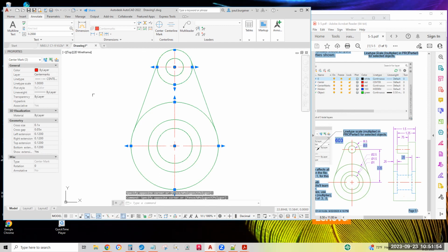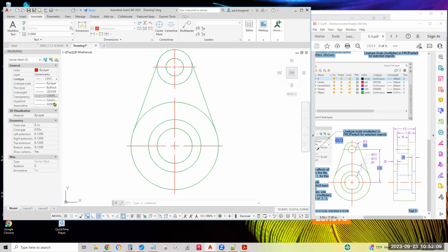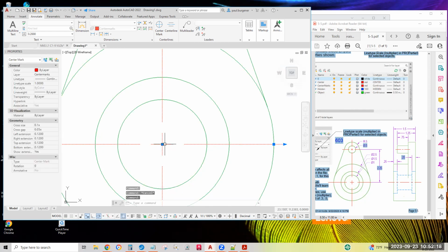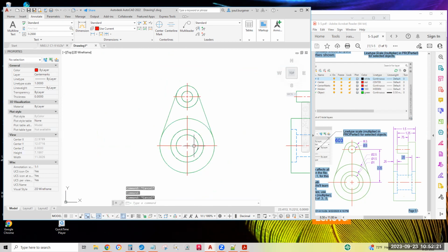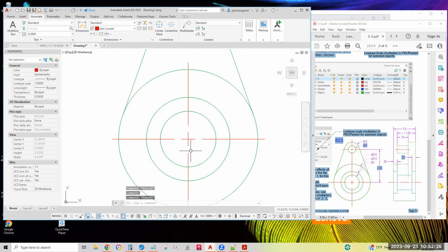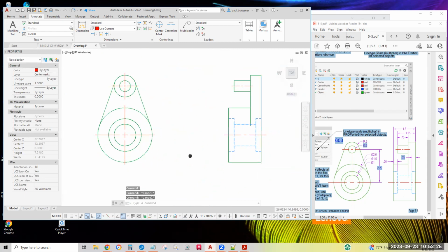anyway, to be on the safe side, I'm going to change the line type of these 2 lines from center to that they came in on, even though I didn't load center to. They came in on the center to, added center to the menu. I want to change them to continuous because these gaps are not part of the line. The center mark is a new type of item that has those gaps in it, regardless of the LT scale. Anyway,